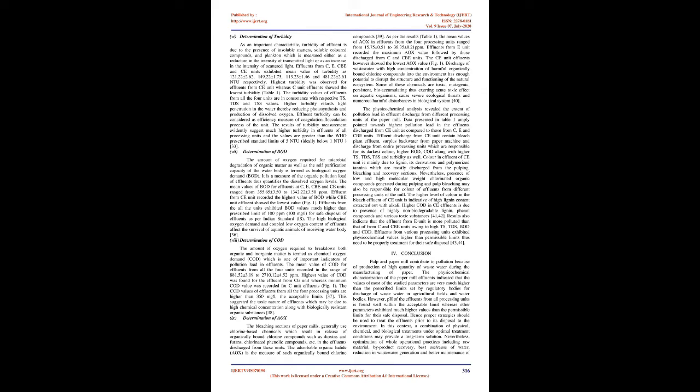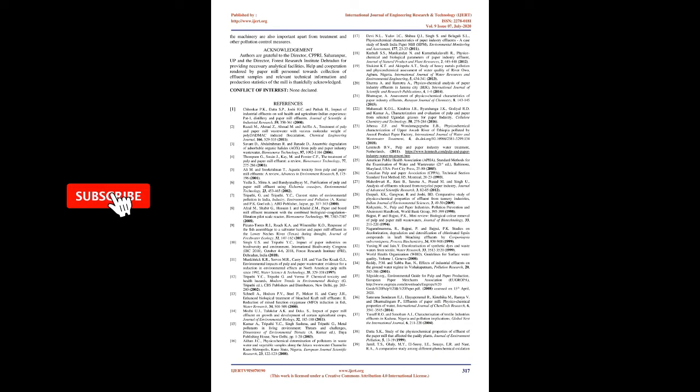34. V. Determination of TSS. The undissolved matters including fibers, inorganic fillers, pigments, etc. in the effluents signify their total suspended solids, TSS. The mean TSS contents of effluents from C, E, CB, and CE units varied from 200.22 ± 2.01 to 1220.15 ± 3.15 ppm. Effluents from CE unit showed the highest value of TSS, followed by CB and E units. C unit effluents however recorded the lowest TSS, Fig. 1.